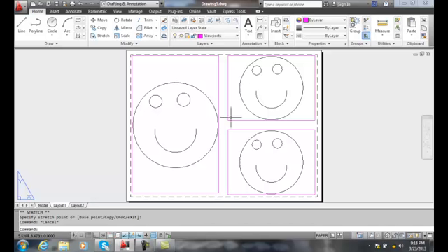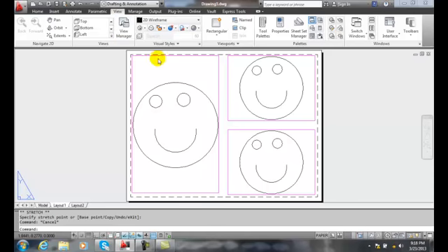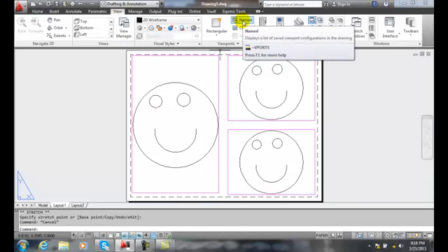the top view, and then the upper right would be an isometric view. So a great way to use to create viewports is to use the Viewport dialog box, and it's found in the View tab in the upper right hand corner called Named.